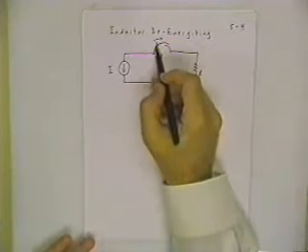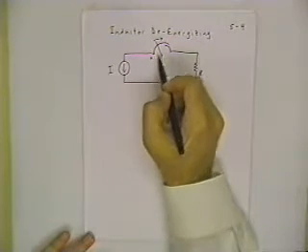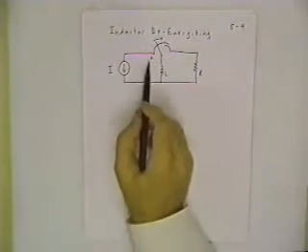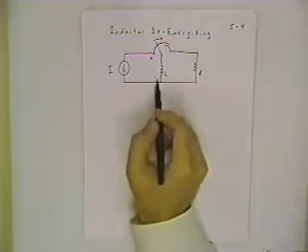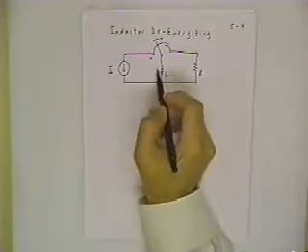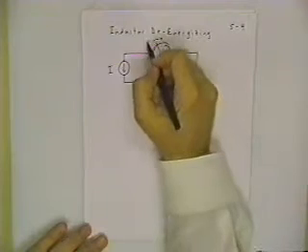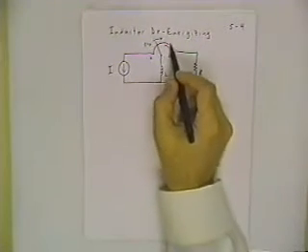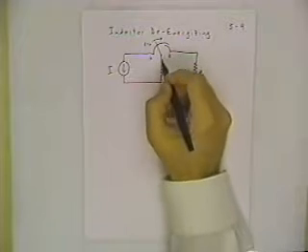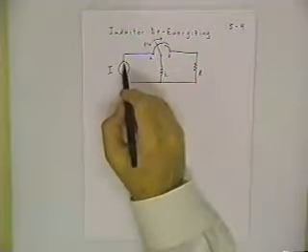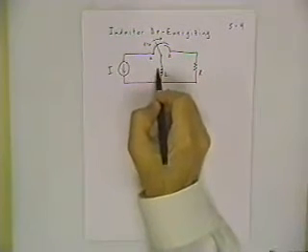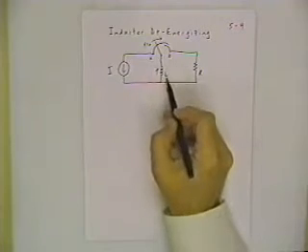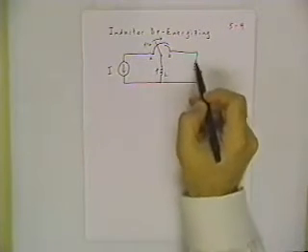Now, the whole point is, when the switch is in position A and we leave it there for a very long time, then this inductor is going to have I amps through it. So what I can say is at t equals 0, I slide the switch all the way over to position B, and now the current that was going this way through the inductor is now the current that's going to be energizing this loop.